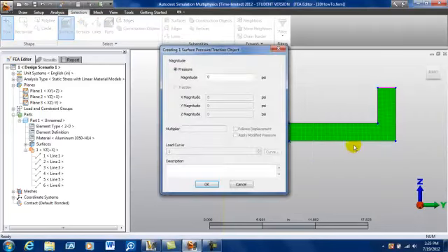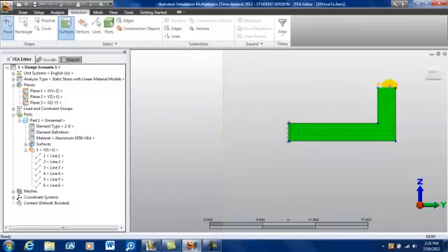We can do a surface pressure traction. So let's do a surface pressure. Now if you know the force that is applied to it, let's say it's a point load, you know it's 500 pounds, you can calculate the area of that surface and then convert it to pressure. I'm just trying to do something really simple to give us some experience in how this works. So I'm going to have a distributed surface load applied as a pressure, magnitude 100 psi, and it'll be normal to the surface. We'll click OK. It's showing a letter P. So we've got that pressure load applied. This should be enough for us to solve our problem.